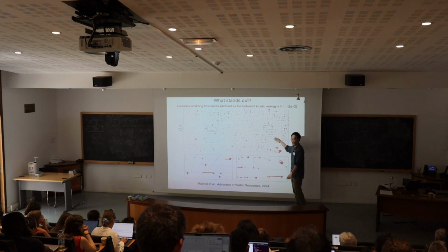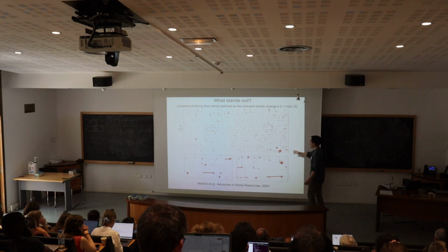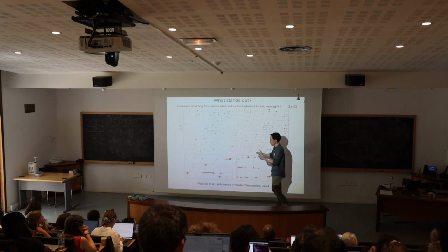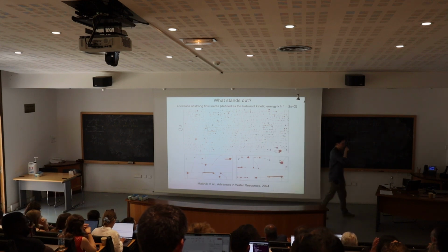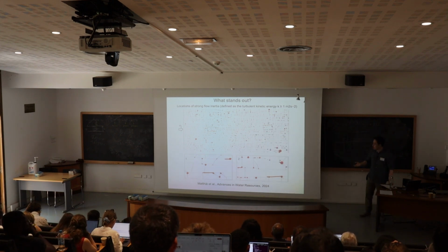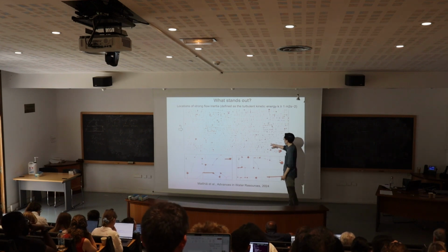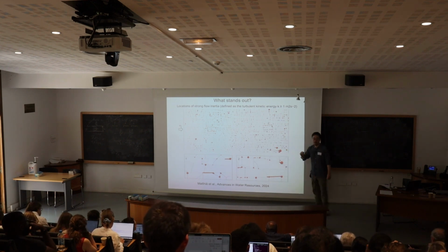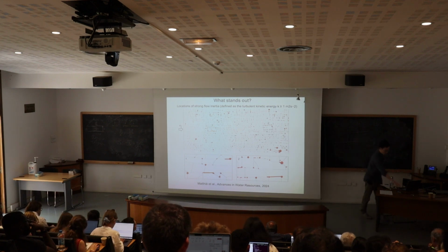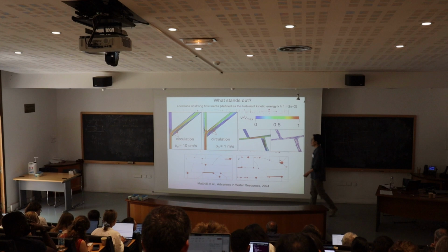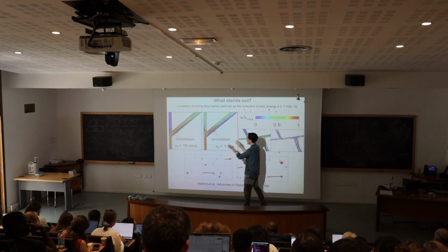So I thought this could be a nice backup study that shows why fracture intersections are particularly important, because that's where the inertia effect magnifies. And that's where the fluid can actively mix and a lot of reaction hotspots can occur. So why is it at fracture intersections? If you zoom in, that's where the flows either converge or diverge, right?